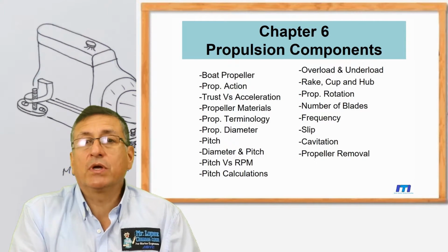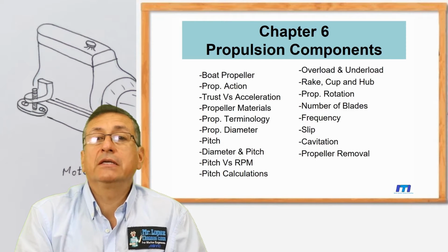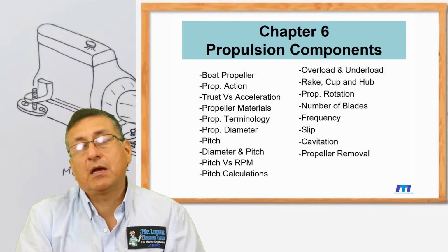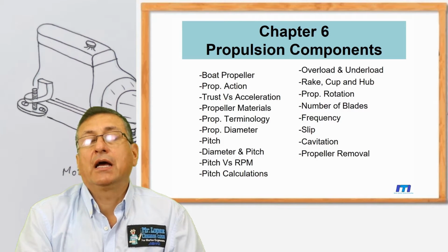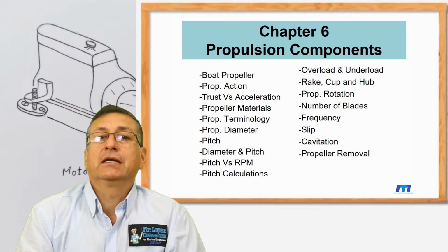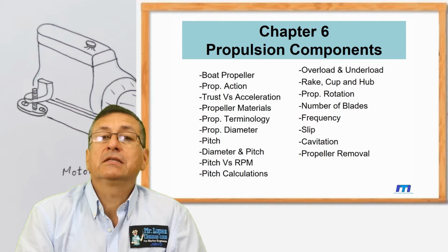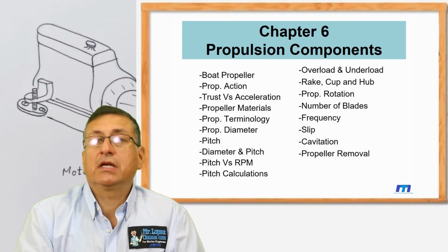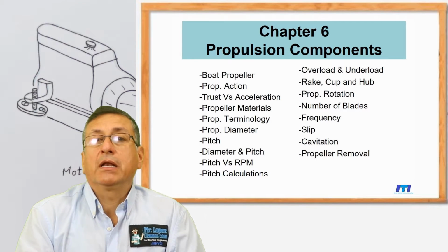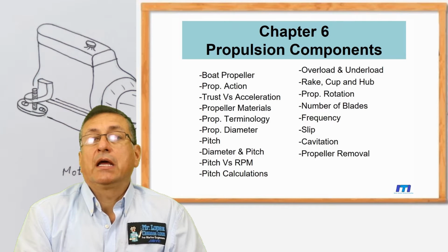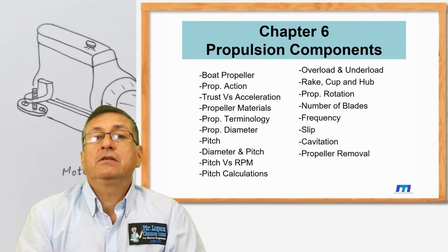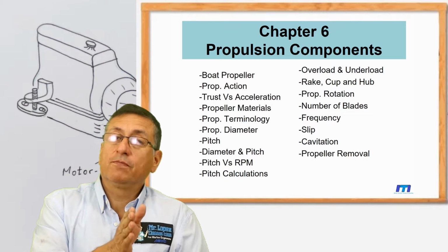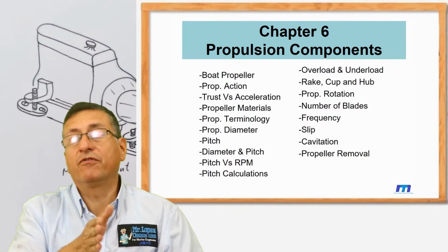In the strut, we are going to analyze the procedure to replace the cutlass bearing, the different types of cutlass bearing. And also we are going to analyze the procedure to install the zincs, the zincs located in between both struts. It's important to install the zincs properly. Alright, and the couplings, the different types of couplings. And with this episode we finish the analysis in particular of each component.